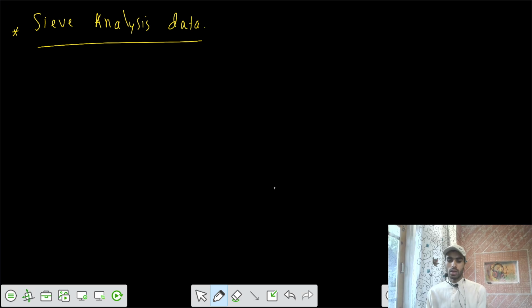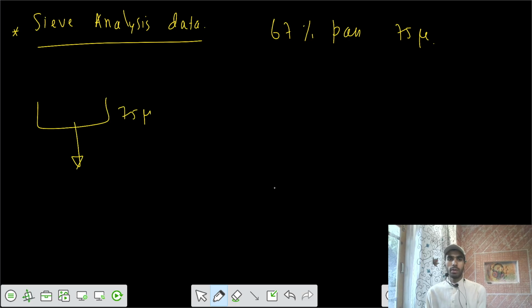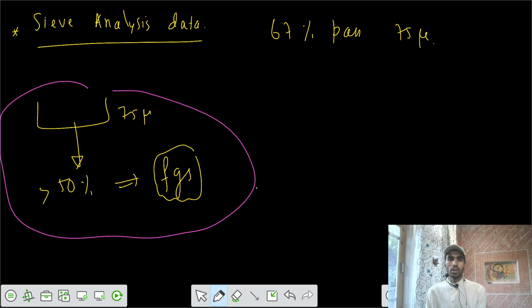Let's take one more problem. We have sieve analysis data. Sieve analysis we have performed, and the data is given to you. What is the data? It says that 67% of the particles pass the 75 micron sieve. So with the 75 micron sieve, more than 50% pass, which means it's a fine grained soil. So this is the solution. Let's write that this is the solution.